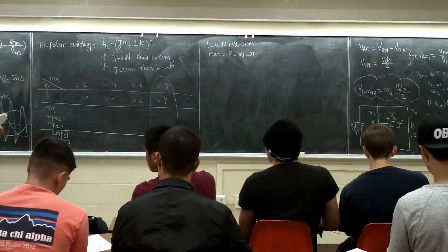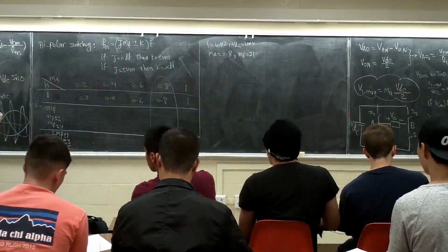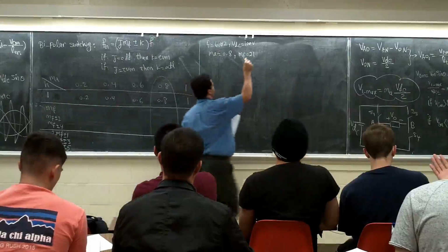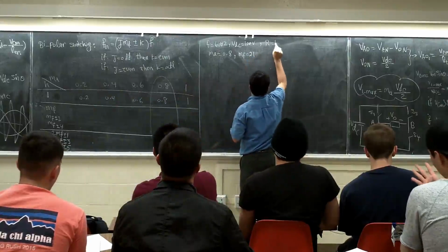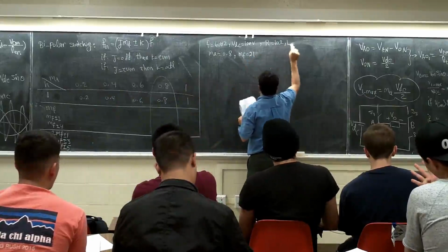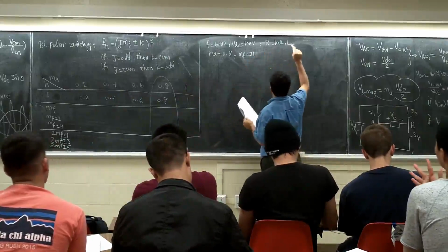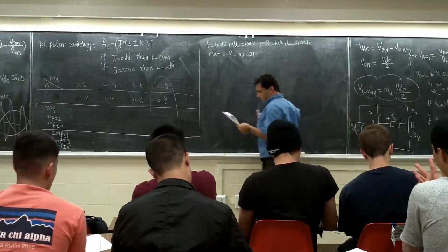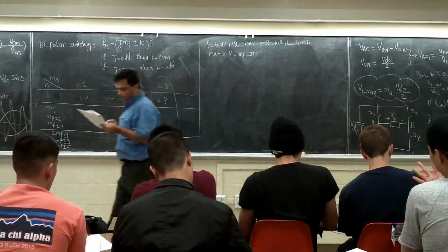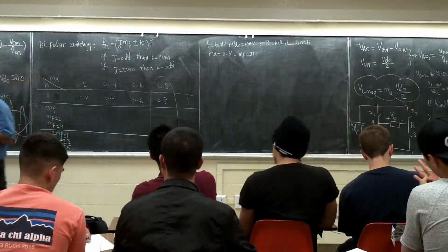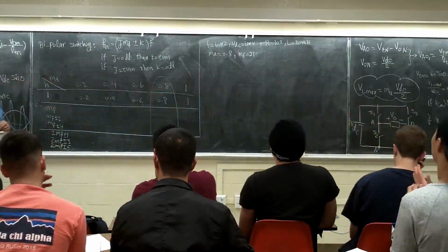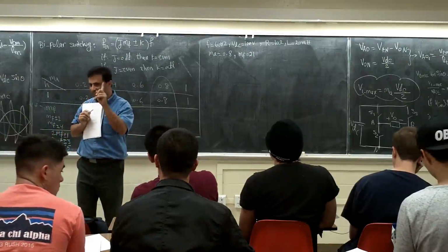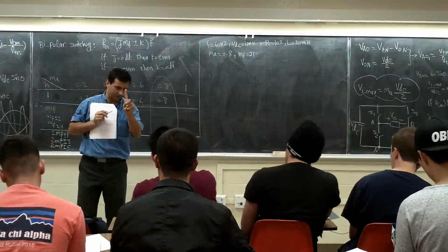Now, the load has a resistance of 10 ohm, so R is 10, and L is 20 millihenry. Determine the amplitude of the 60 Hertz component of the output voltage. 60 Hertz is which one? It's the fundamental, right? 60 Hertz is the number one harmonic, right?